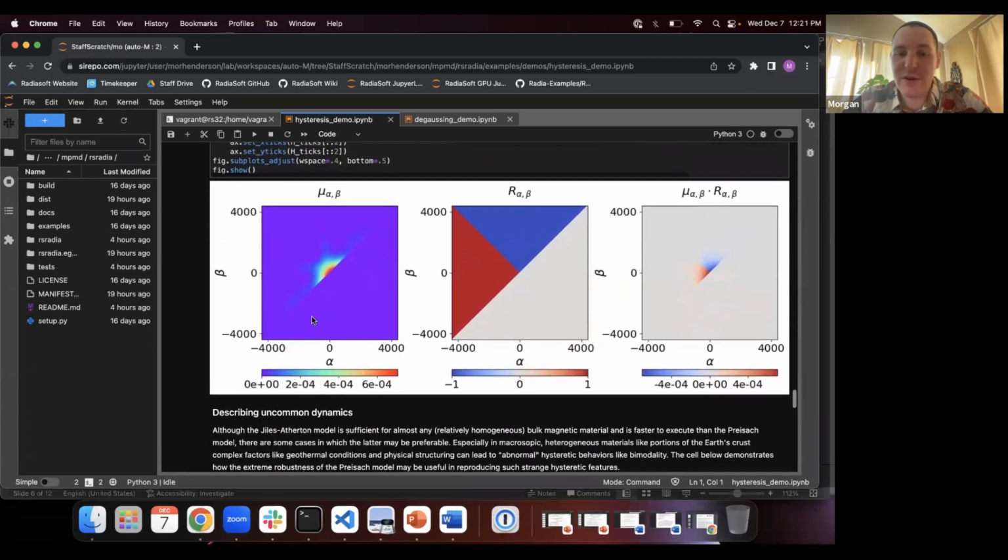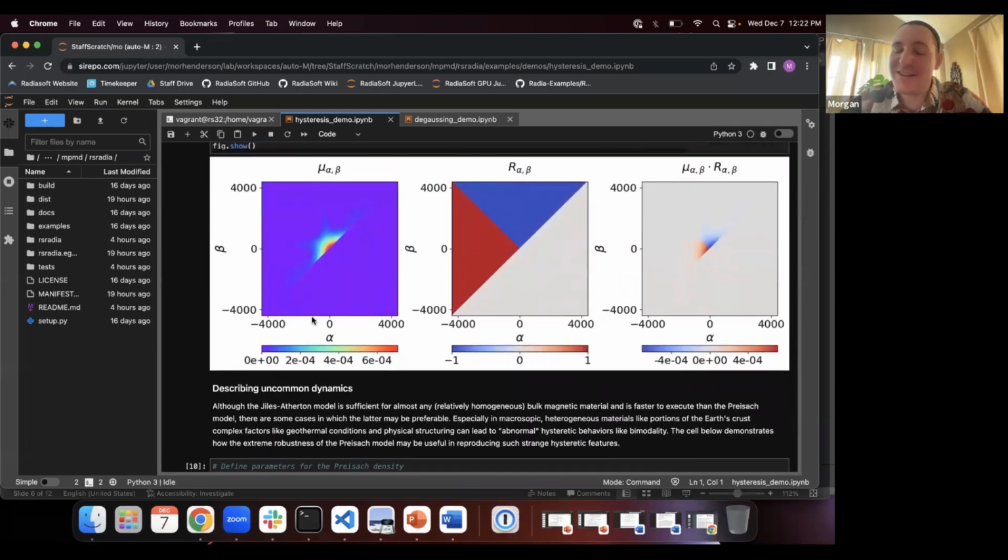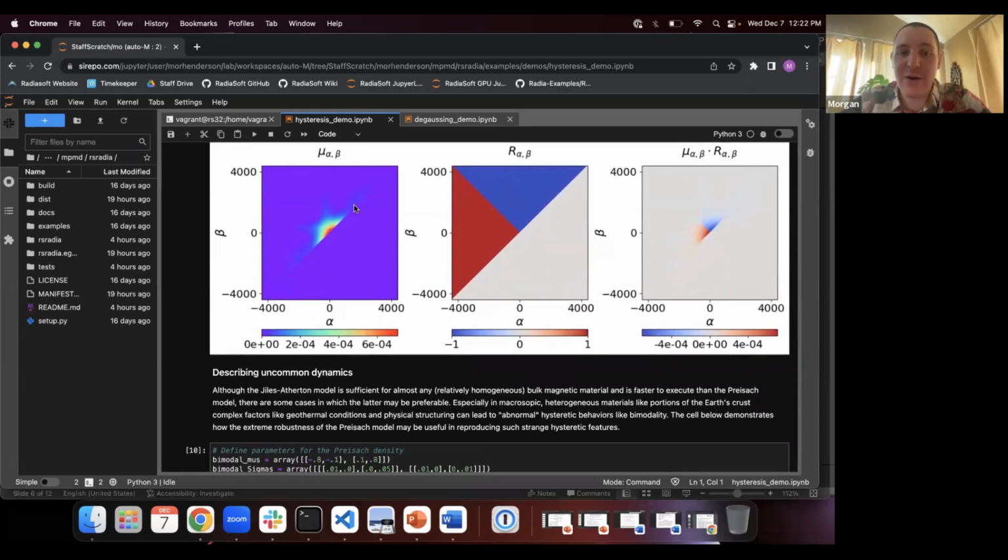And so a little bit of graphic help here to see what this really looks like, because this is not the most intuitive model. Here we've got our hysteron density distribution, which looks quite strange. You can imagine it might be difficult to come up with this on your own if you aren't fitting to experimental values for the curve. But we have a completely blank lower triangle, since we should never have a turn off value lower than a turn on value.